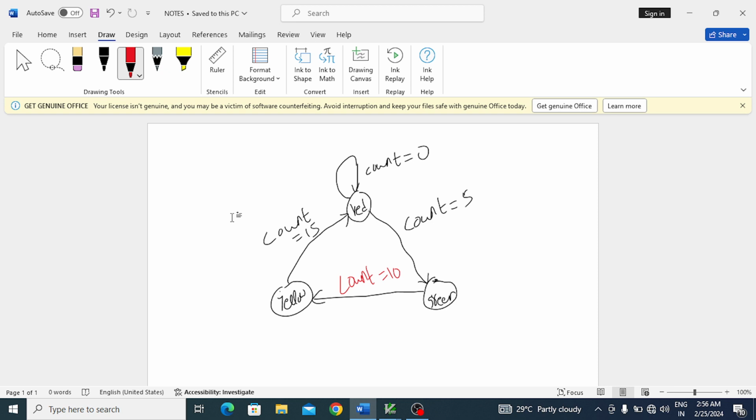So in general, in the traffic light controller, the electronic circuit is a counter. We stay in a particular state for some particular time by counting clock pulses. When I explained counters in digital, I told you counting means counting clock pulses. So we measure the time by counting clock pulses, and I gave the traffic light controller as an example. Suppose the traffic light controller wants to be in the red state for 5 seconds.